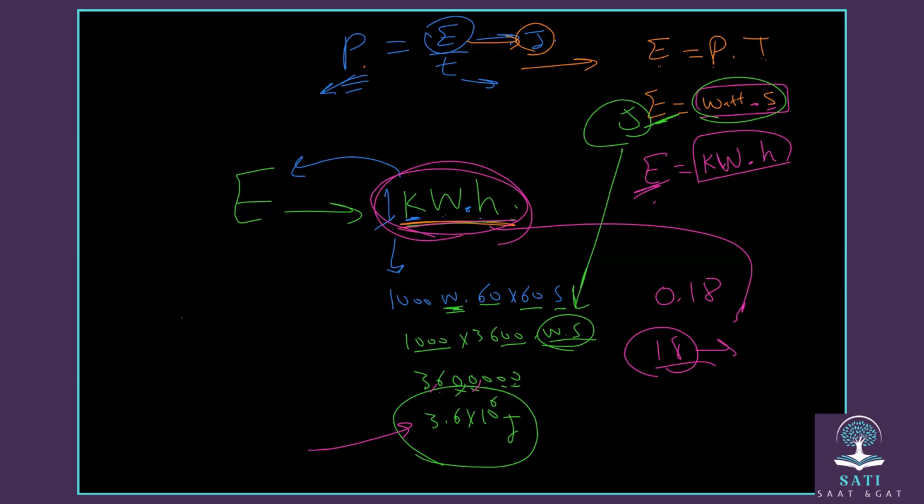That means there will be a loss in the energy over this long distance. So in order to reduce this loss of energy, we need to reduce the resistance. How do we reduce the resistance? We reduce the resistance by choosing good materials in manufacturing the wires. This is number one. Number two, instead of using a wire with a low cross-sectional area, we use thicker ones that have a larger cross-sectional area. Number three, we need to increase the voltage.